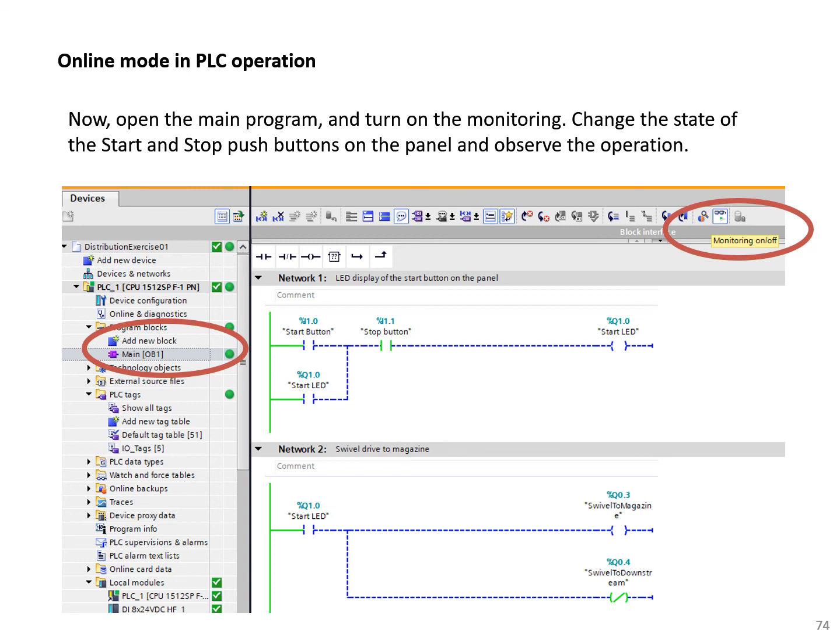Okay, it's a bit difficult to test the program in PLC sim because in a real device you have so many sensors and inputs, and you need to understand the sequence of which one first should be modified to either 0 or 1, and then test your program step by step as you proceed.